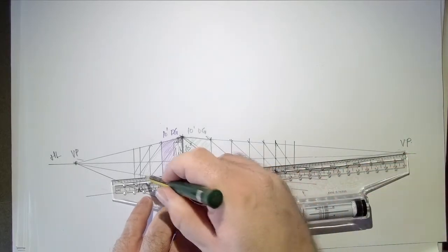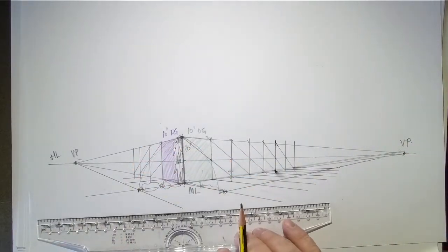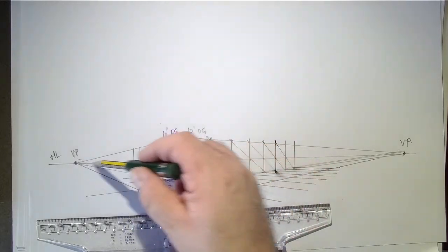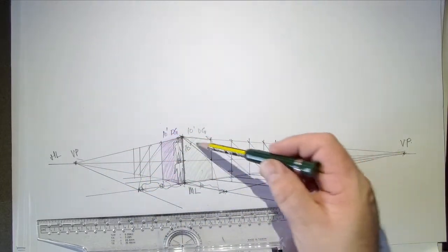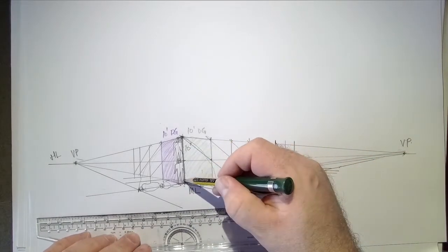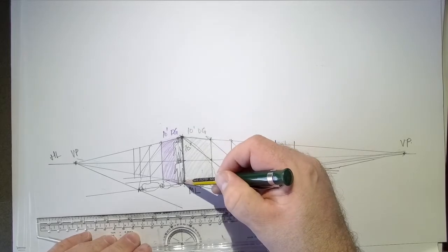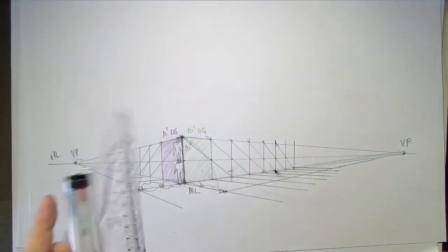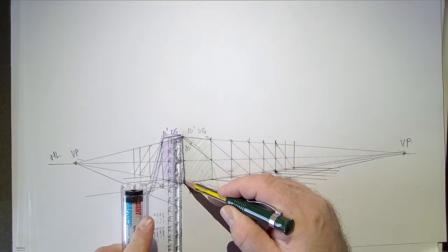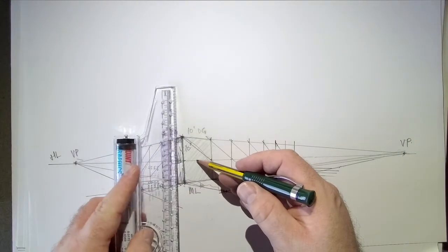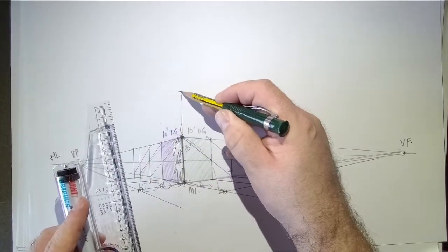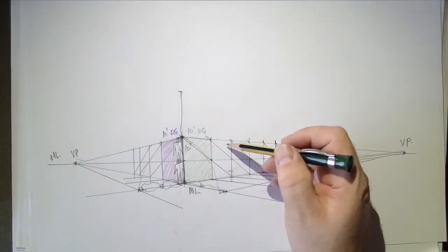Running out of space here. All right. So we have representations of 10 feet in depth vanishing to the left vanishing point, 10 feet in depth vanishing to the right vanishing point. We can also project up. Anything contacting this measuring line can be translated up. Just in terms of measuring it, again, I'm just under 2 inches, so I'll just repeat that measurement, like so. That'll give me the next 10 feet of space.